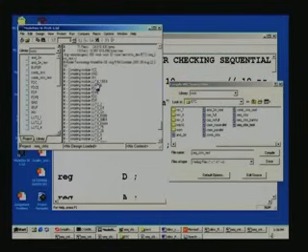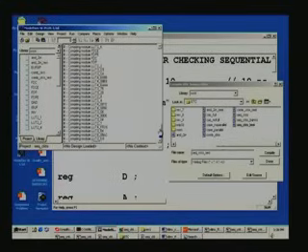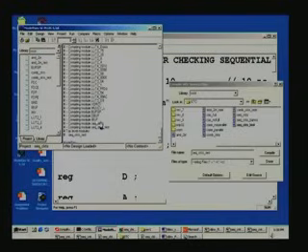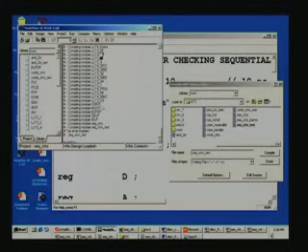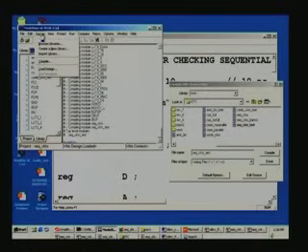You are already familiar with the synthesis, having created LUT4, LUT2 and FDC, FDP, then once again LUT, D flip flops for FDP, etc., and so many LUTs, then mux, buffer, input buffer, output buffer. It has taken all this and compiled. That is because we have mentioned .vm in the test bench. Earlier, if it were .v, it would not have reported all this. So, that means it has right now taken your .vm, which was the optimized file by synthesis, as the source file, and the next step is to load this design file.